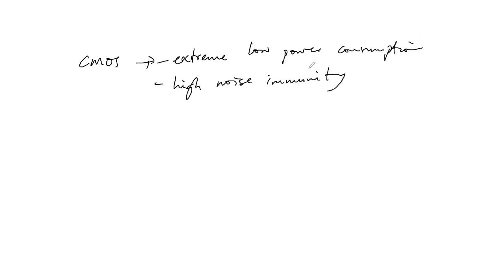So unlike the TTL logic, CMOS logic requires two supply voltages, okay? So we have VDD. Now in typical logic design, the VDD ranges from positive 3 volts to about positive 16 volts. Yes. While the V sub SS is usually grounded, right?